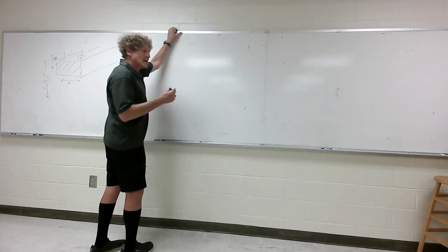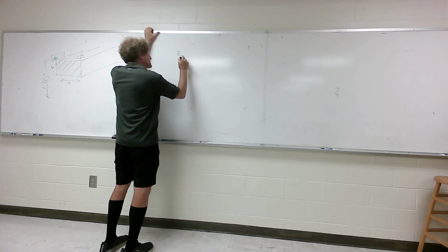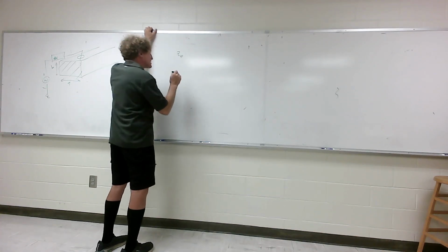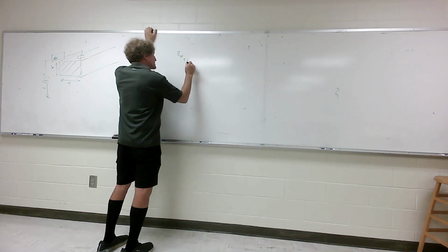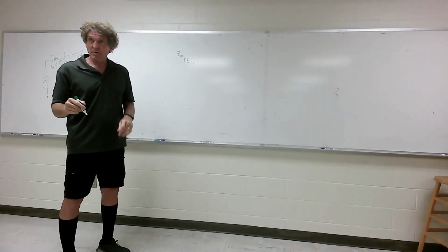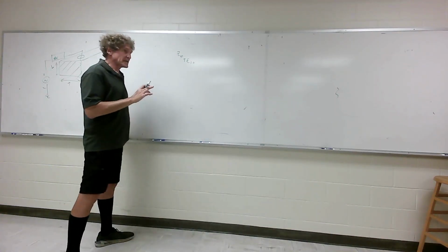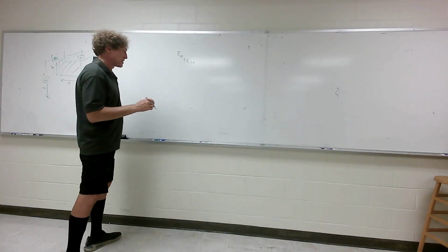So if we're going to use a waveguide to do that, the first thing we have to calculate is the characteristic impedance of the waveguide. I'll call it Z0. And for a rectangular guide, it's almost always in the TE10 mode. Y'all with me on this? So the way you go about that is you don't want to excite any mode but the 1 mode.